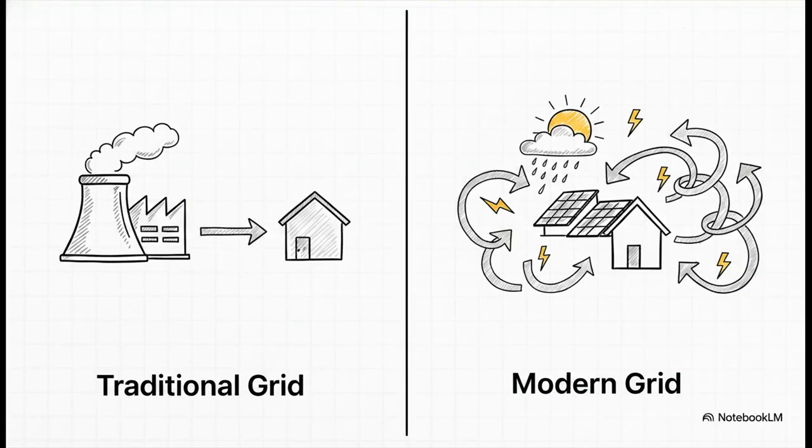Okay, here's where we bring all this lofty physics crashing back down to reality. You see, the typical electrical distribution grid was originally designed for a passive one-way traffic system. Power flows steadily from the substation straight out to your house. But the minute we start including renewable distributed generators, we introduce chaotic two-way power flows. When a solar array faces short fluctuations in irradiance, say from a passing cloud, it fundamentally throws off power quality and total harmonic distortion. Furthermore, if a short-circuit fault happens, inverter interface generators quickly inject reactive power, which can actually disrupt the performance of our critical safety relays.